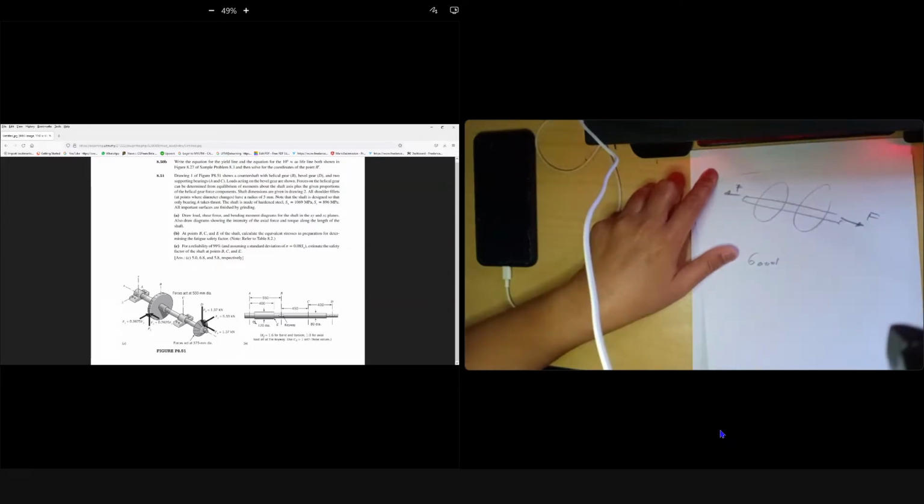So at shoulder E, do we have axial or not? There is an argument on that, because the bearing A is designed to support axial. So we have axial at this B here, Fx 1.37, then up until B we have another Fx of 0.26. You can find this Fx.